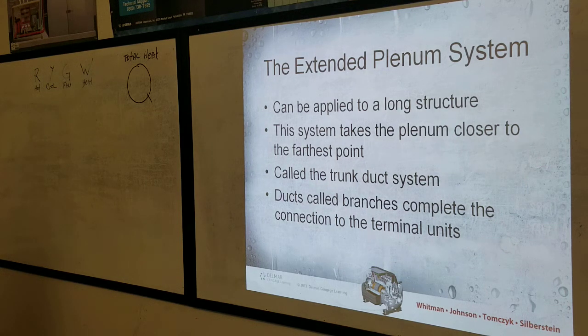Hey, quick question, if we're replacing a whole AC unit, are we supposed to go in there and look at the duct system and make sure that's all good as well inside the home? You're required to, actually, you're required to get a duct pressure test, according to the state of California. The US government wants you to make sure that there's no leaks or minimal leaks in that duct system. And to do that, do you do it on top of the roof, or do you have to go inside the attic? You gotta go in the house to do it.